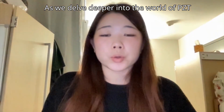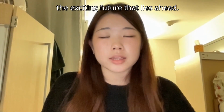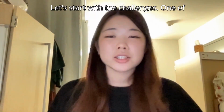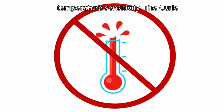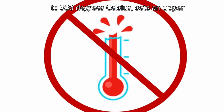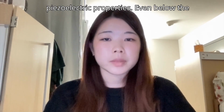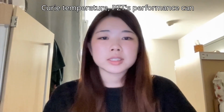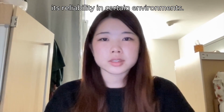As we delve deeper into the world of PZT, or lead zirconate titanate, it's crucial to understand both its limitations and the exciting future that lies ahead. Let's start with the challenges. One of the primary limitations of PZT is its temperature sensitivity. The Curie temperature, typically ranging from 150 to 350 degrees Celsius, sets an upper limit for high temperature applications. Beyond this point, PZT loses its piezoelectric properties. Even below the Curie temperature, PZT's performance can degrade as temperatures rise, affecting its reliability in certain environments.